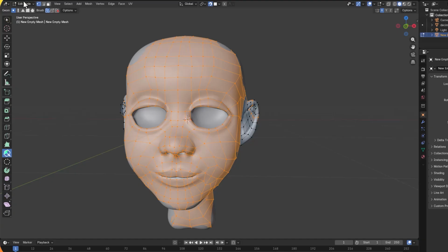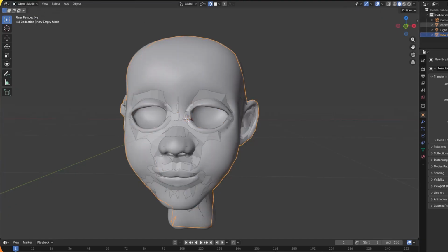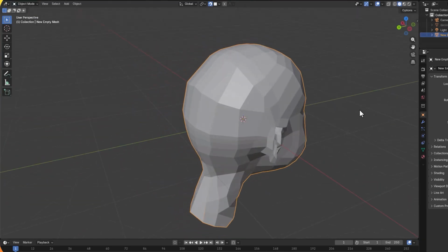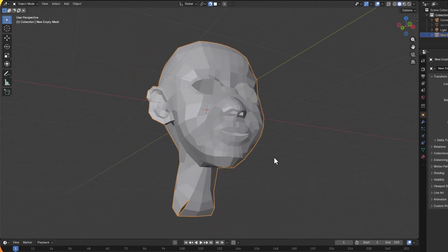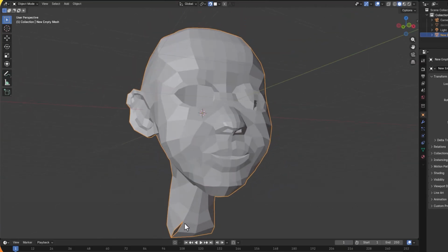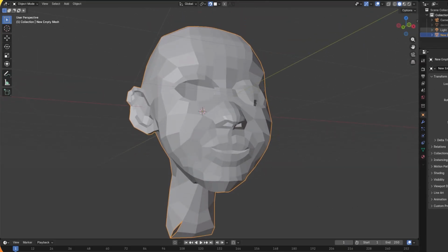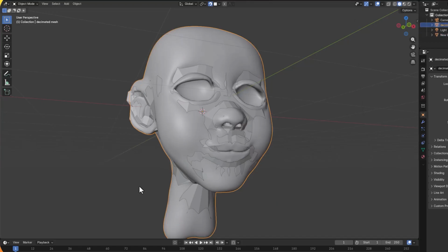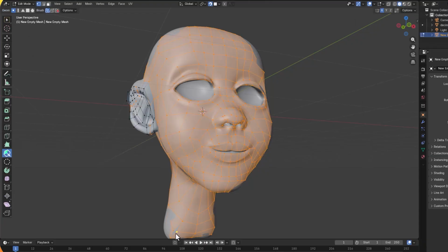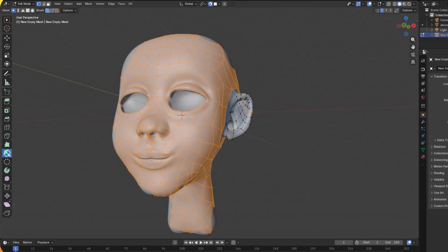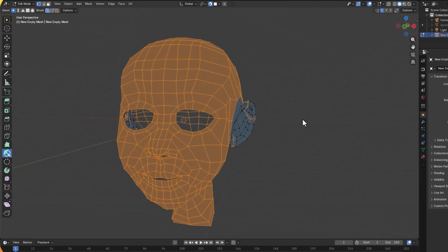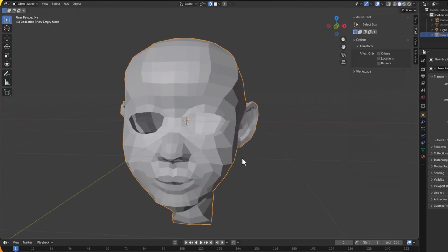Next, what we're going to do, I'll come back to the object mode and try to hide the shape over there of the decimated object. You see there's open space there, which means that we never closed the gap. So I can come back and select this retopology mesh, come to the edit mode. We need to pull that there. So that's good.